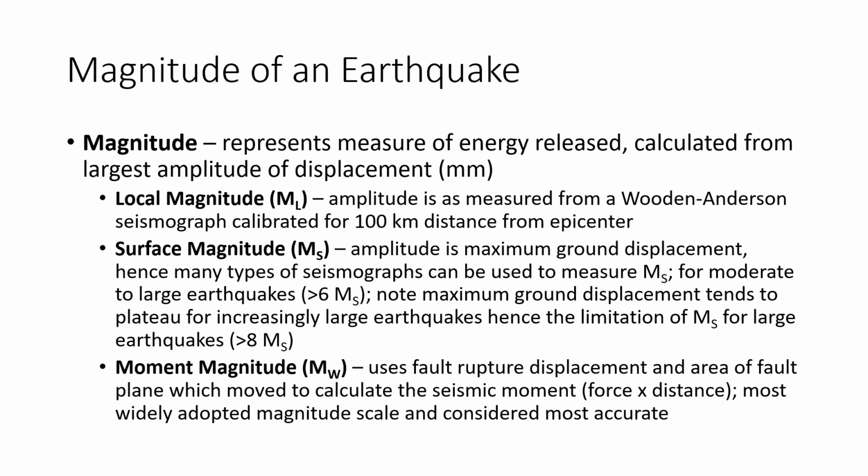In this case, the earthquake event with a larger fault plane area will have a bigger moment magnitude, even if they have the same fault rupture displacement. So that's the advantage of your moment magnitude scale, that it accounts for the actual size of the fault plane.